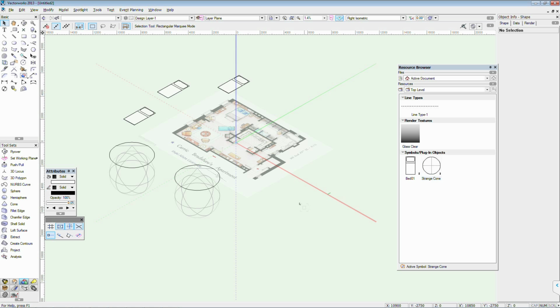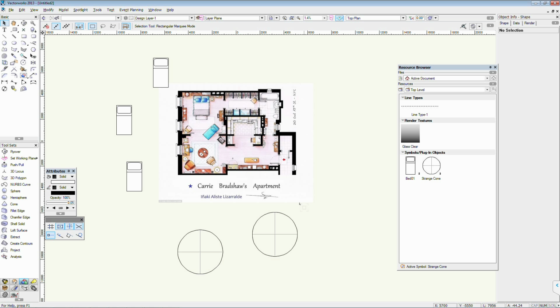Now, that's all well and good. The advantage of 2D and 3D symbols is that they can merge together. And what you'll find is that if you have a really, really detailed 3D object, sometimes when you're in this plan view moving things around, you really don't want to have to render all of those details that lie underneath. Vectorworks has a solution for this, which is when you're in a plan view, like I'm in now, it represents an object as a 2D component, and when you need the 3D data, it will pull the 3D data out for you.